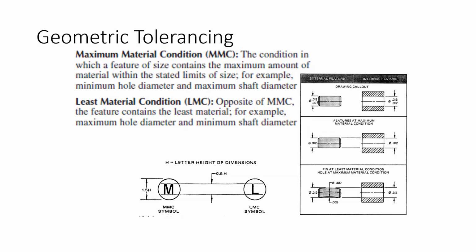When that shaft diameter tolerance is at the minimum or the maximum, it's going to be the largest it can be, right? So that part will be heavier when that shaft diameter is at the upper limit of its tolerance. What if I've got a part with a hole in it? Now we're talking maximum material condition. It'd be the minimum hole that makes maximum material condition.